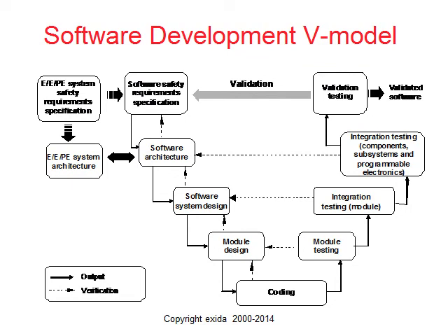And if we take, for example, 61508 says you must do tool justification. Any tools are classified as category T1, T2, T3, depending on the impact they can have on design. For any tools used in product development, and that can be CAD tools, compilers, simulation tools, you've got to do a justification that that tool isn't going to introduce an error.